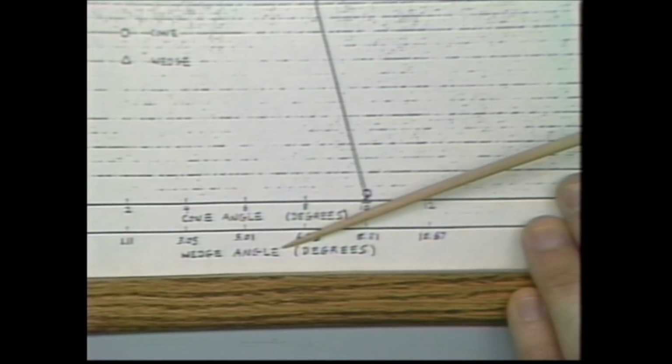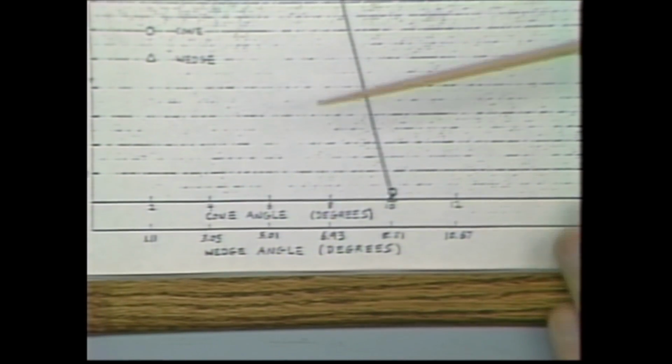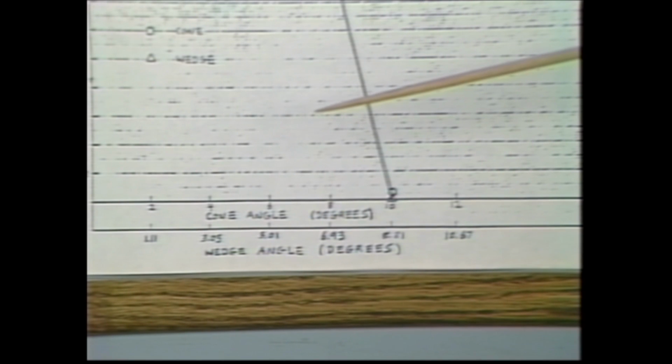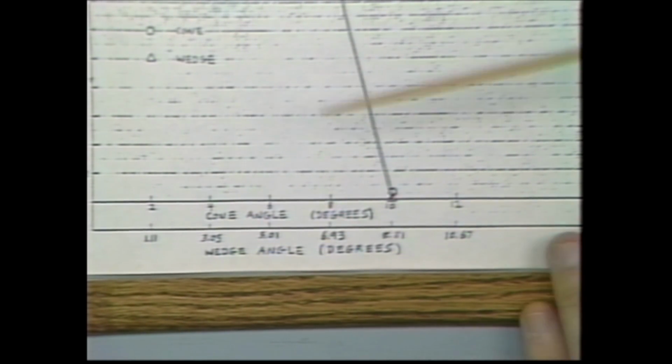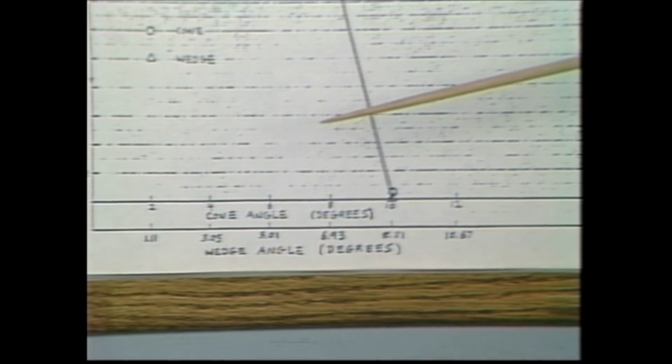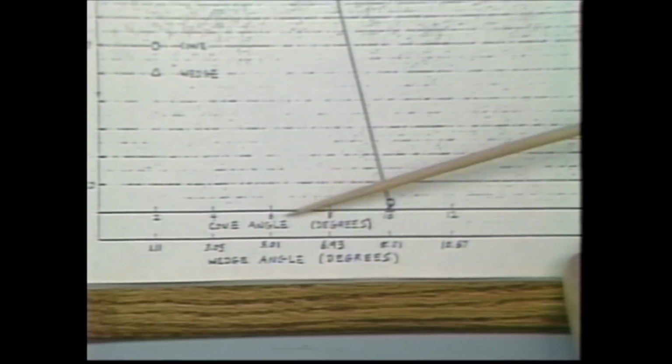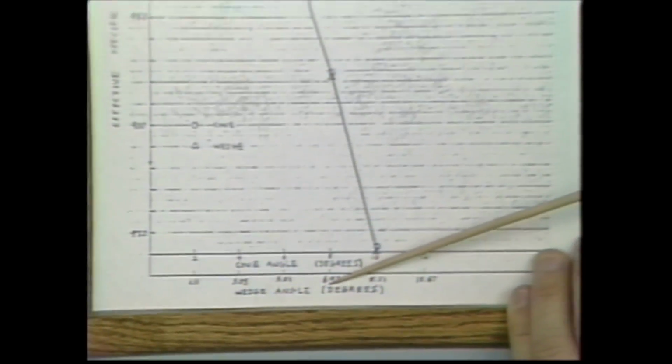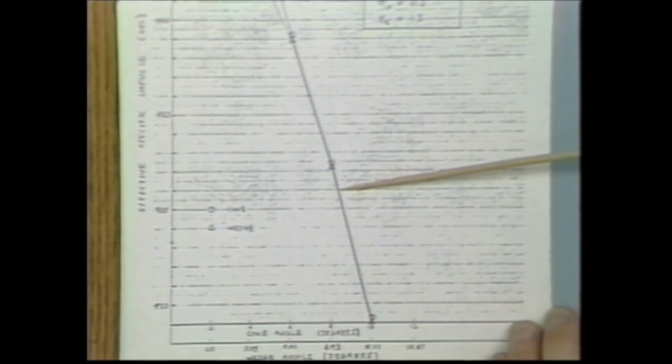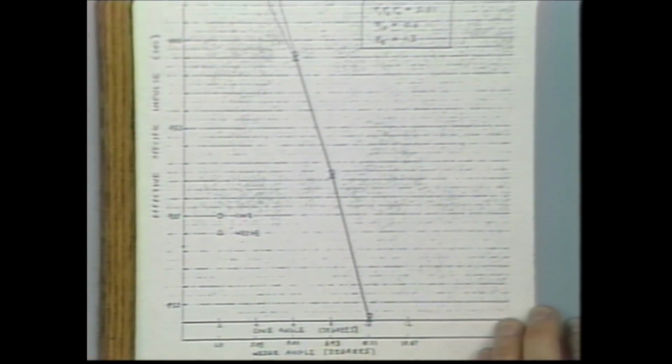For cone angles, down here you'll see the cone angle and the wedge angle at the bottom. I've plotted these in terms of equivalent cones and wedges. I define equivalence as having the same losses across them, and it turns out they have the same contraction ratio, or contracting of the area ratio of the flow, and this is the correspondence shown down here. For equivalent cones and wedges, you don't really see much of a difference in performance. At very low angles, perhaps cones would be a little bit higher performance.